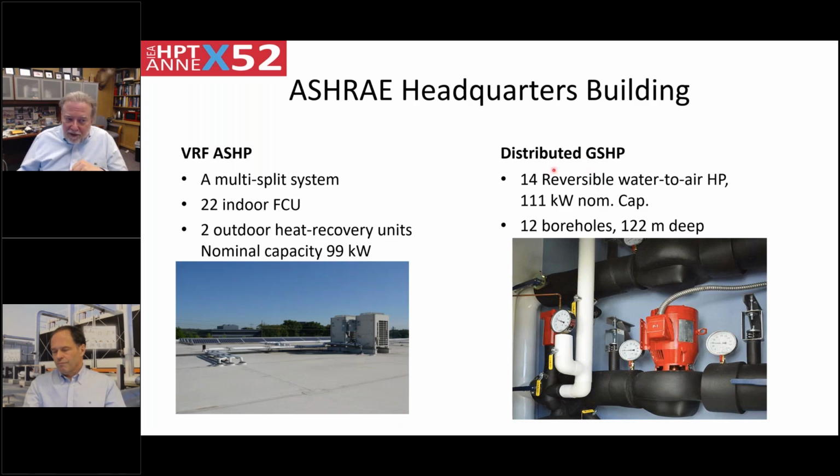As a result of this system design, most of the heat pumps sit above the ceiling panel tiles, so they're hidden from view. And the only mechanical room is actually a closet, which has, in this case, a glass door on it so anyone could observe the settings. And here are a couple of pumps that are used to circulate water between the ground heat exchanger and the heat pumps.